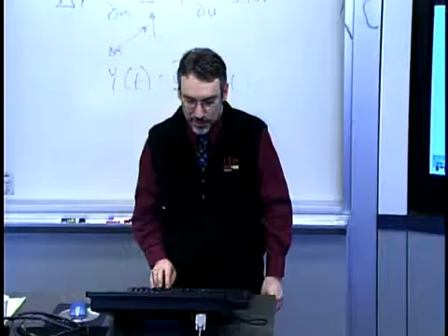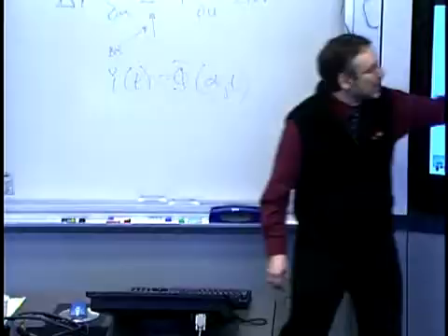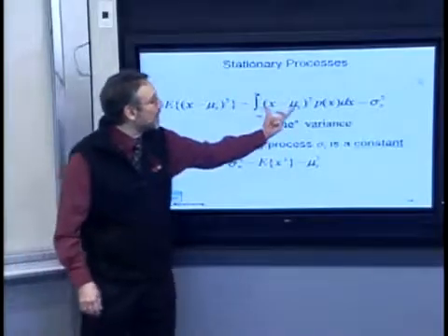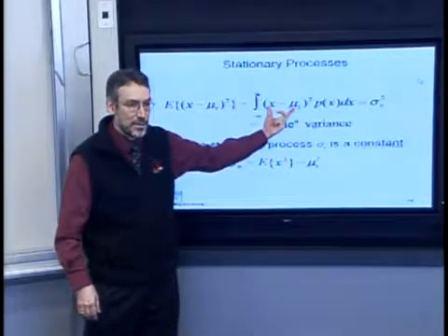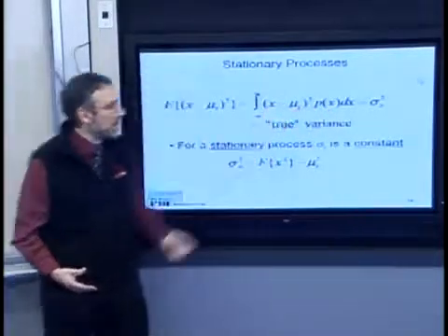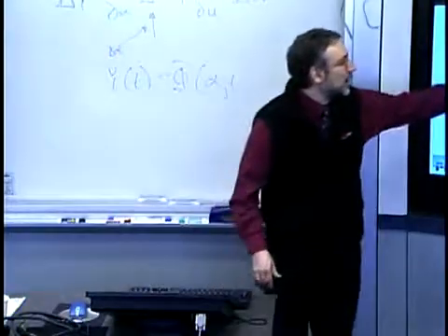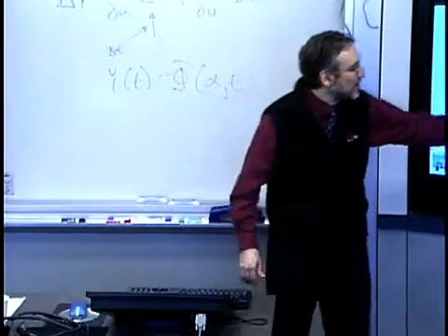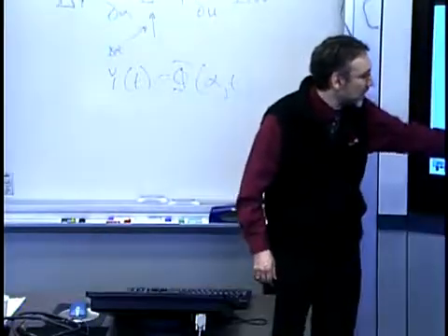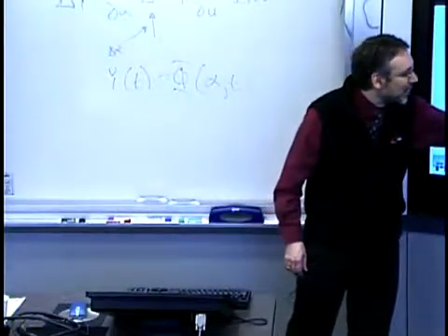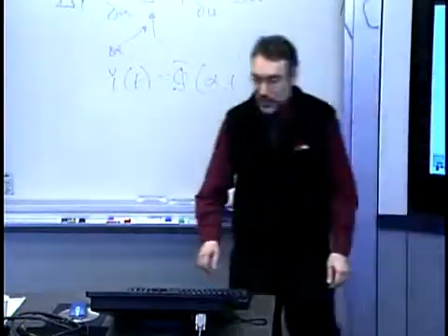Similarly, in the case when it's a stationary process, the variance, defined here as the second moment, right? The expectation of the distance squared of your data from the mean, the ensemble expectation of that is the variance. That's just the definition. And in the stationary case, that is also a constant of the process. It has a nice alternative description if you work through the mathematics, where it can also be calculated as the expectation of the square of your data minus the mean squared.